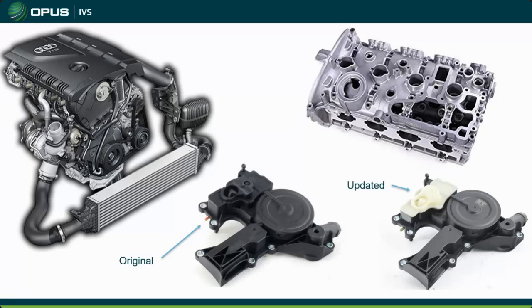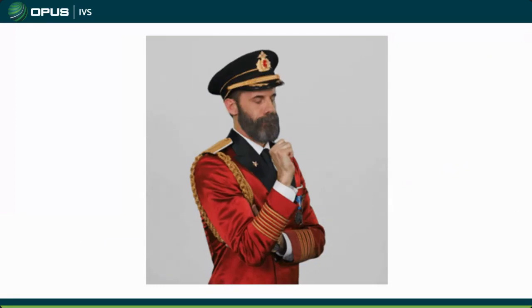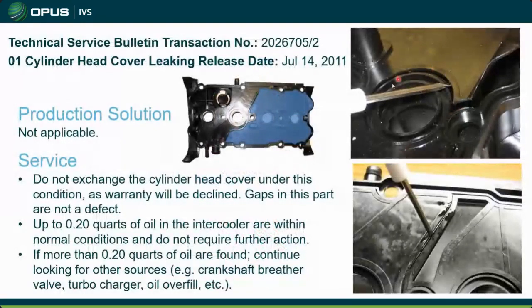faults for lean mixtures or air in the system, and you have no external leak. You'll have no external leak, but what you actually have is an internal leak, and you're getting false air through this valve cover. So if you have one of these systems and you're sure that it's tight and that you've got no external leaks, but you're still getting these faults as if you had a vacuum leak, you might think about pulling this valve cover off and checking to see if it's cracked wide open, because you could have a vacuum leak. It's just internal. You're not pulling air from outside per se. So something to definitely keep an eye on. And I don't know who wrote this TSB, but that doesn't make much sense to me.